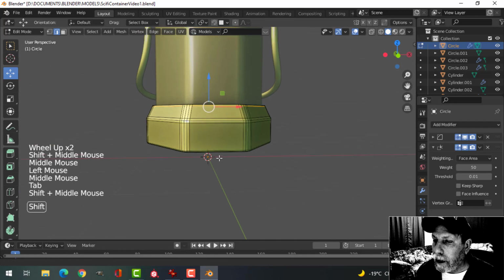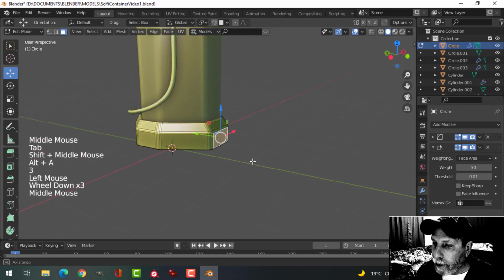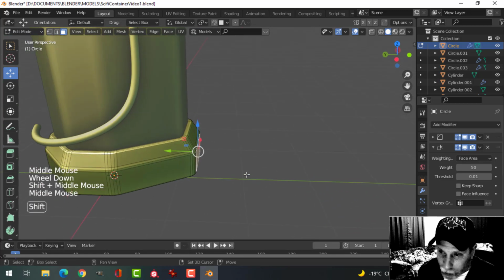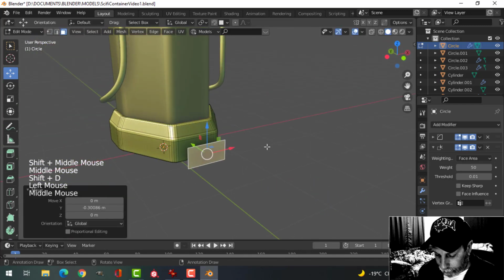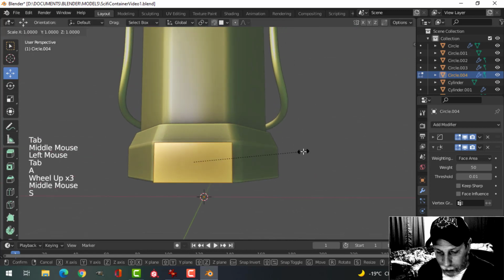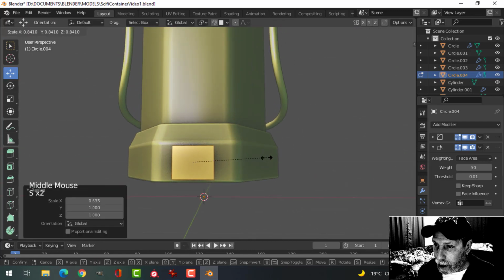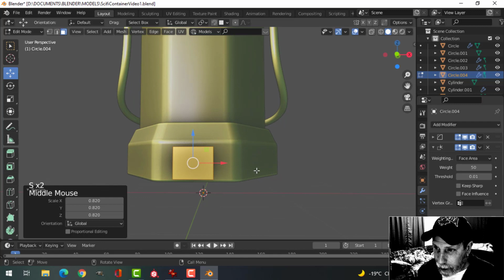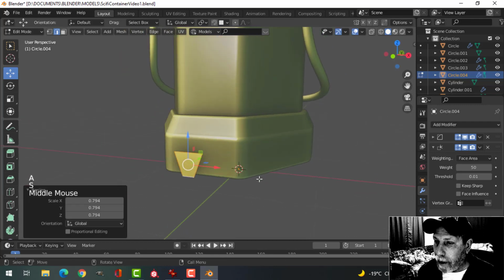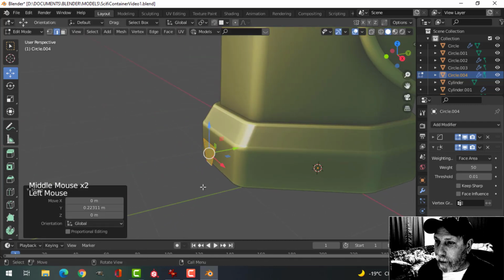Okay, just like this. So here's what I'm gonna do. I'm gonna select this face, and I'm gonna use it instead of bringing in a plane of my own. So there, got it already positioned. I'm gonna scale this in the X. I'm gonna scale it completely, like you'd make an arrow, sort of sci-fi arrow.